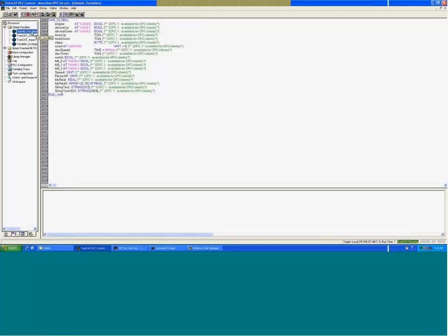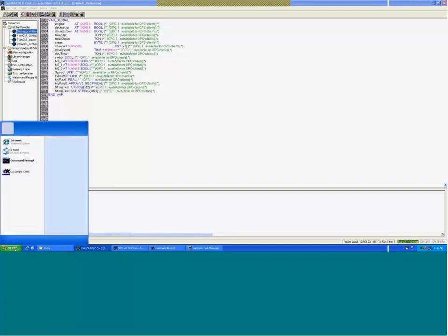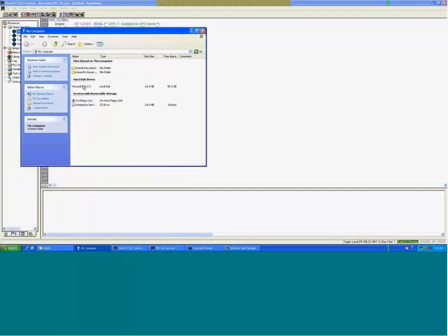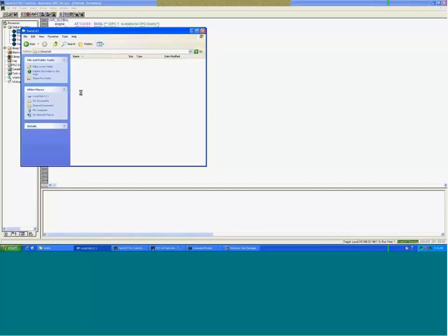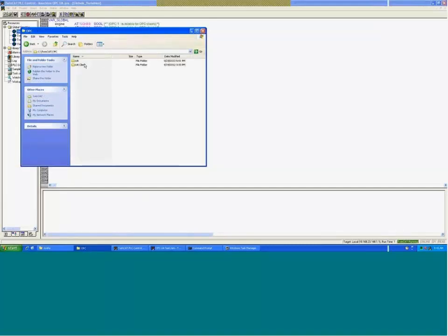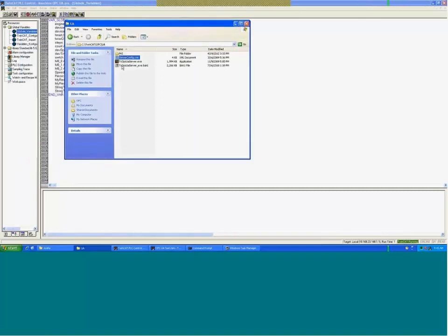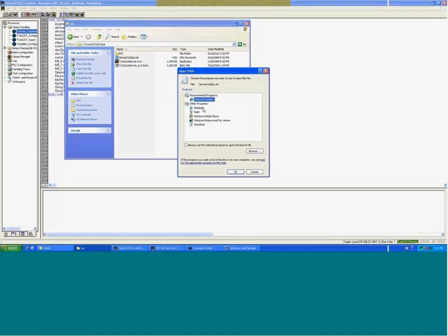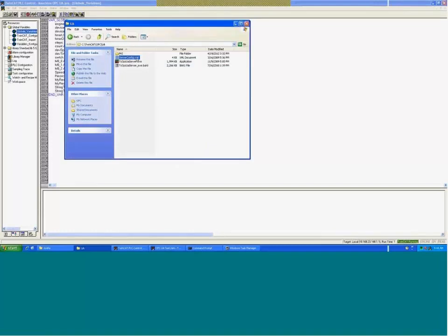So pretty much what you have to do is this. On the TwinCAT side, you're going to have to download and install the OPC UA server. Okay? So as you install, you're going to have the OPC folder and the subfolder UA. You have a license for it. Okay? And then there are some OPC configurations you do. That's TwinCAT 2. So I'm going to open this, actually, let me just open it in the browser first.